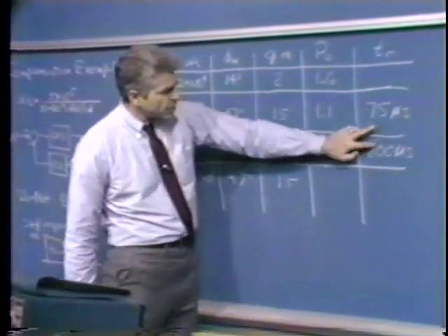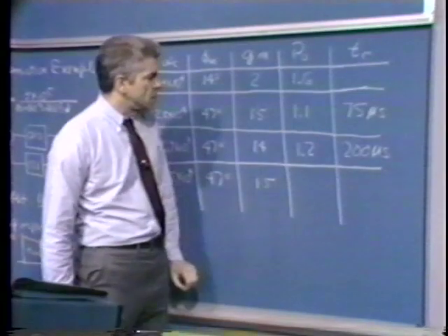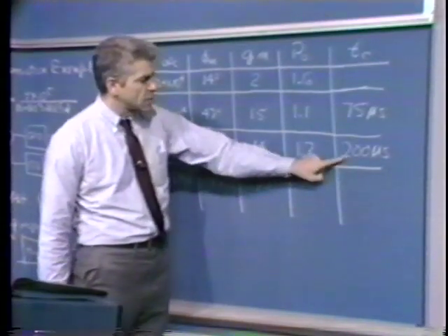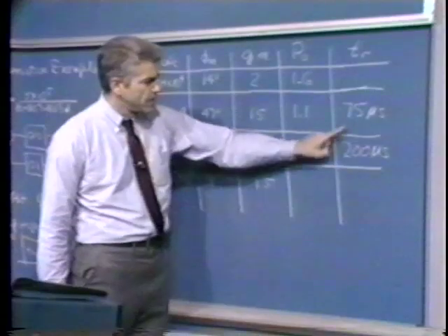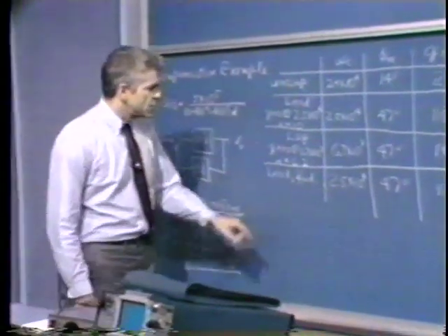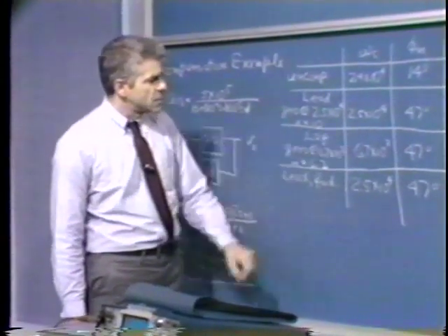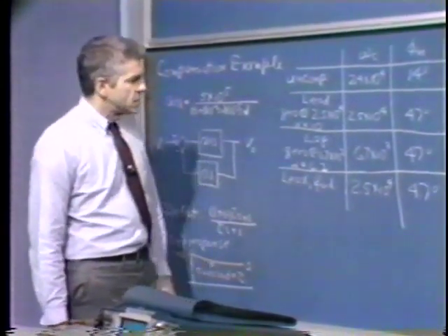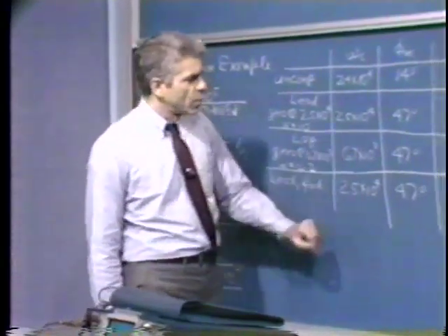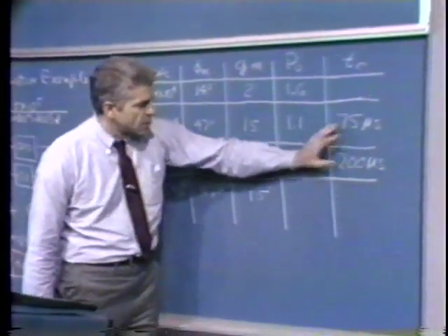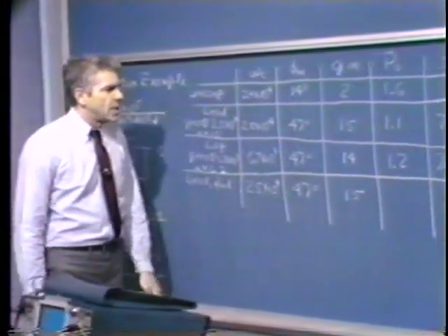Furthermore, there's roughly a 3-to-1 difference in speed of response, the lag compensated system being a factor of about 3 slower, whereas there's roughly a 4-to-1 ratio in crossover frequencies. And so that's a little bit bothersome. Here there's very nearly 4-to-1 ratio in crossover frequencies, actually a little less than a 3-to-1 ratio in speed of response. That's a little bit disturbing. It'd be nice to sweep this under the rug and mumble experimental error, but it's really not that. It's more fundamental than that.